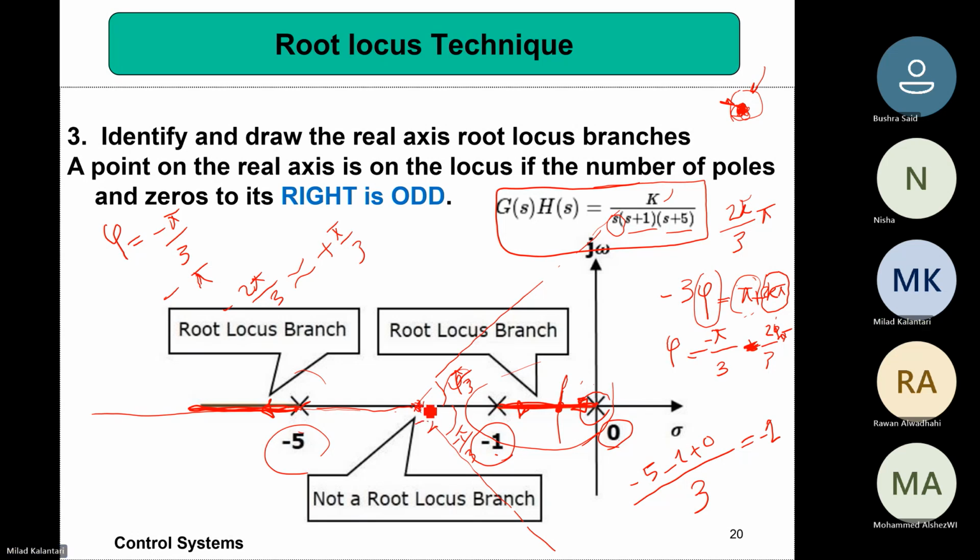So this is what we can see when the poles are very far, right? From very far, we are seeing that there are three asymptotes. And then we expect that the pole at the end is following these three asymptotes, right? So at least for this pole, we initially know that it is going in the correct direction. This pole is supposed to follow these asymptotes.